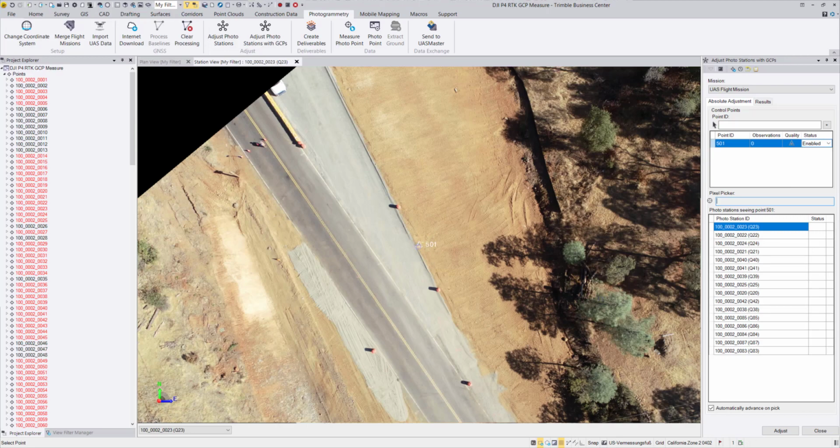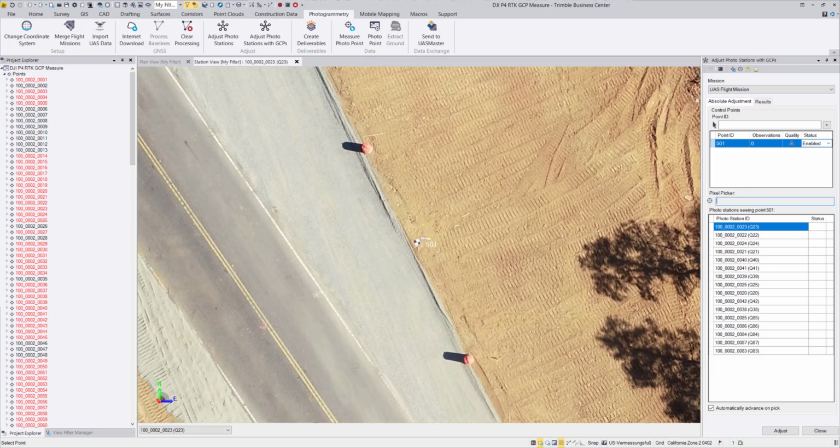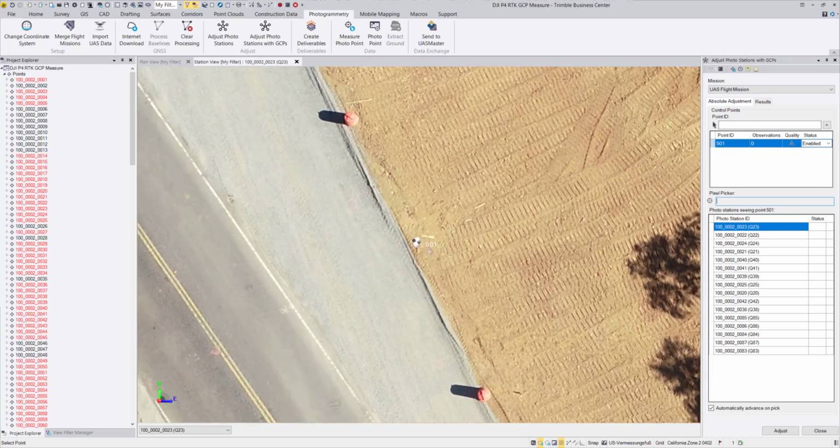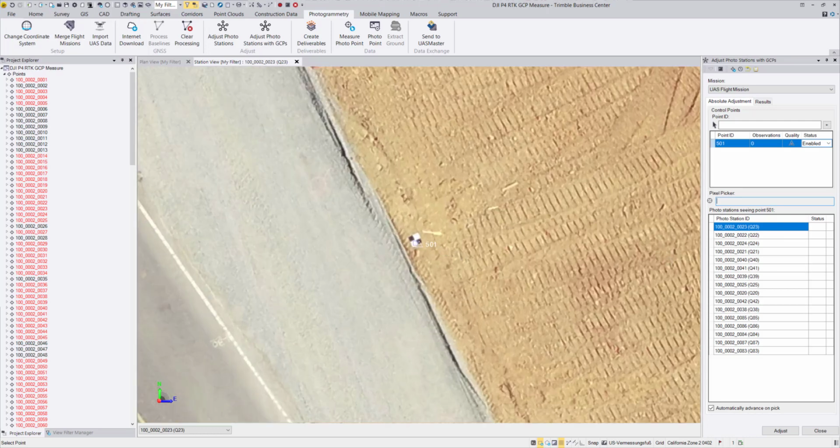At the beginning, we see this white triangle, and this white triangle is the prediction of where our ground control point is displayed in the current orientation state and distortion model of our camera for this project. And you see it's not pitch perfect in the center of it, because we did not use the ground control point itself for our adjustment.